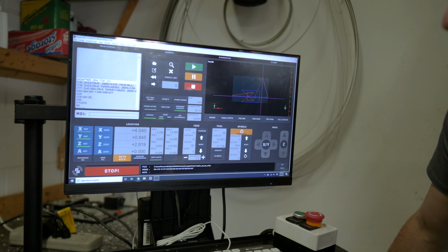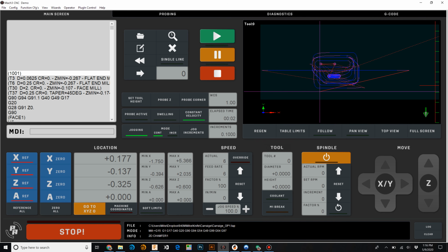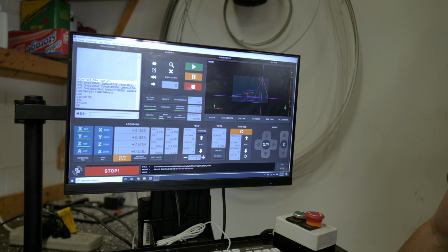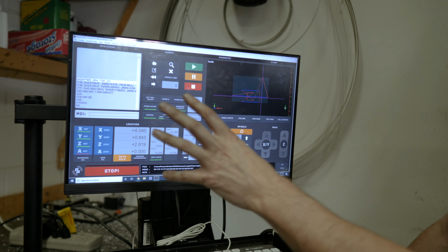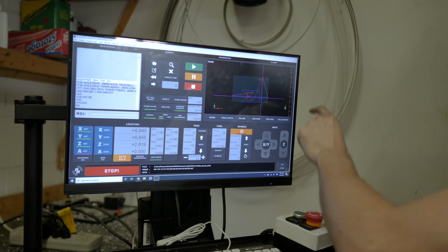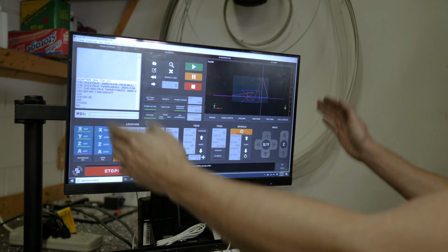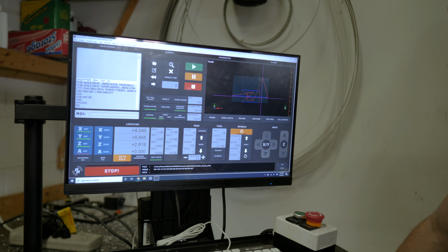First of all, you might be amazed that Mach 3 supports 16:9. And in fact, it sort of does. You can create the screen set to whatever size you want. Now, if you set it to 1920 by 1080, the standard 16:9 high def monitor resolution, it does some really weird scaling, and it took some experimentation to figure out what its real resolution is, which is basically the full resolution minus the start bar and minus the menu bar on top, plus a tiny bit on the sides that it subtracts as well. But once I figured that out, all the text, all the imagery looks nice and clean.